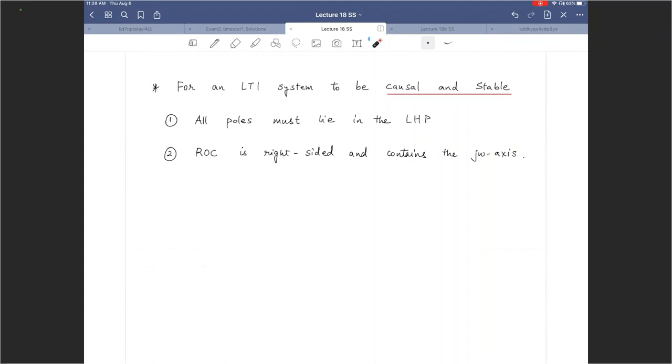So for example, if I quickly draw this out, suppose I have two poles. Let me make the poles complex conjugates of each other. If you have two poles on the left hand side, it's good. Let me also mark these axes: this is sigma, this is the j omega axis. If I have two poles, complex conjugates of each other, I know that I've met the first condition, so it's stable behavior. Where is the region of convergence for this?